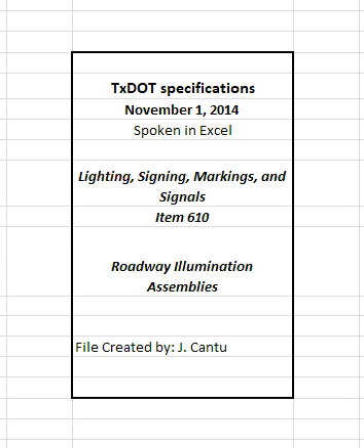Manufacturers may request that the department add their submitted shop drawings and design calculations to a pre-approved list of optional and non-standard pole designs, maintained by the Traffic Operations Division. Hot dip galvanize fabricated pole sections and associated parts in accordance with item 445, galvanizing. Punch or drill holes in steel parts or members, when allowed, before galvanizing. When shown on the plans, paint poles in accordance with the plans for uncoated structures and in accordance with item 445, galvanizing for galvanized structures.